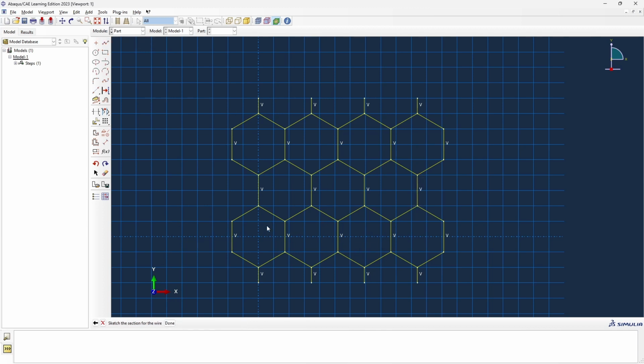So after that's done, you might recall that I deleted this member of the hexagon, and that is because if I copy pasted the entire element again, there would be an overlap at this very specific member, and as I copied these two hexagons to this side, the copied member here, the one that's been affected twice, will spread itself, and that is not something we need because we could fix it by deleting those members, but we could avoid that mess entirely by just doing it from the very beginning.